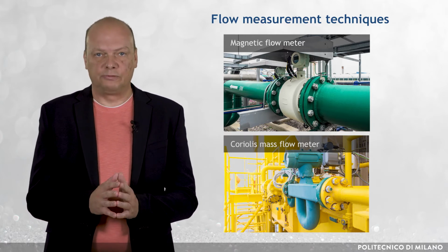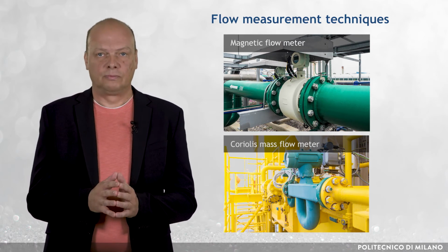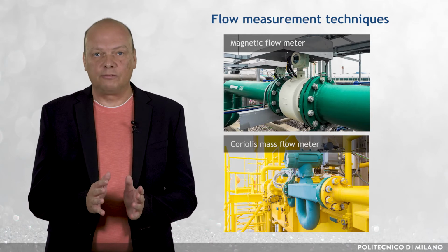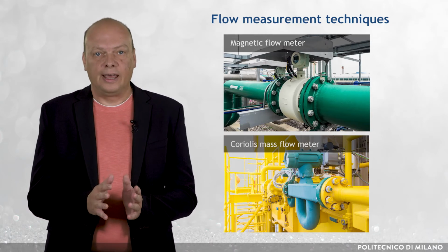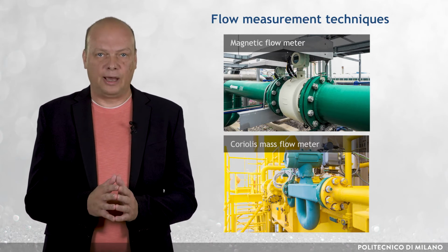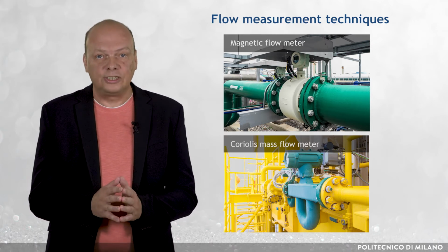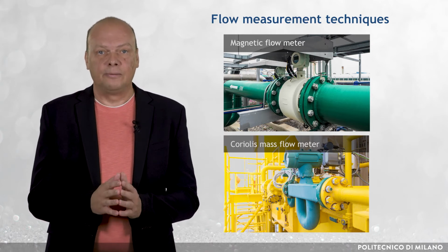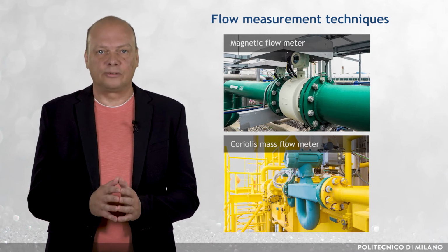They are not suitable for slurries that are strongly erosive or very coarse. Although now available for relatively large pipe sizes, the instrument and installation cost can become very high as the pipe size increases. Despite all of this, the ability to simultaneously measure the density and the flow rate provides an attractive alternative to other instrumentation.